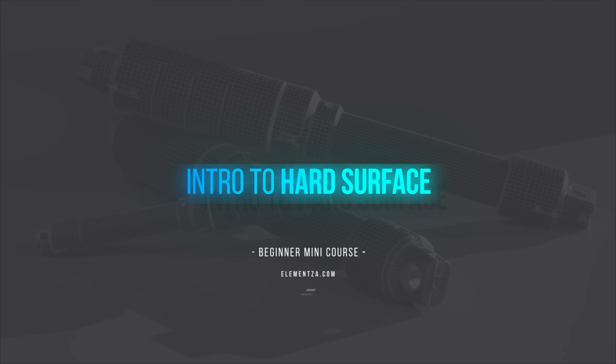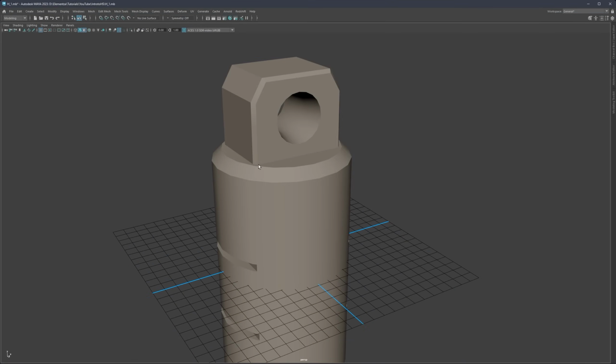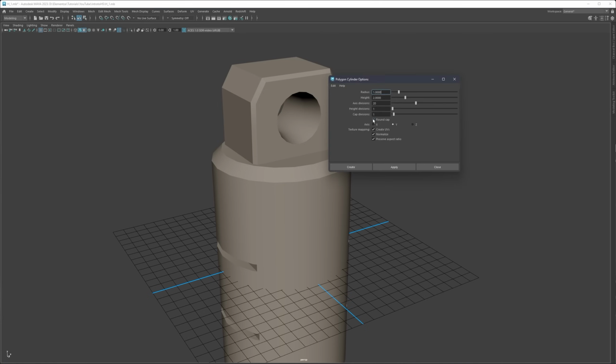Okay, so let's now begin by adding a new cylinder. And again, what we can do is try to test which size is going to fit the best. We started with a cylinder with 20 sides. We can now do maybe 24 and see if that works. So let's go to create a new cylinder, select this little checkbox, go here to axes, divisions, and set 24, hit apply and close.